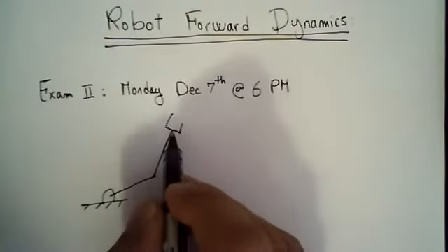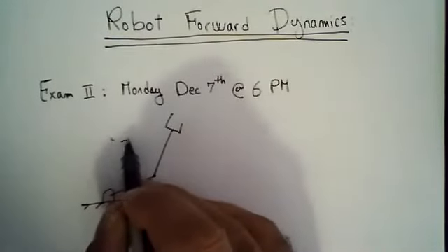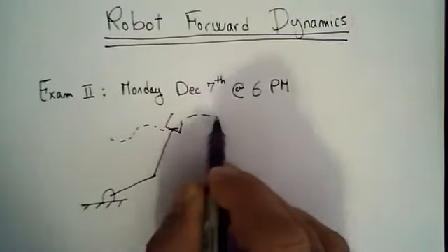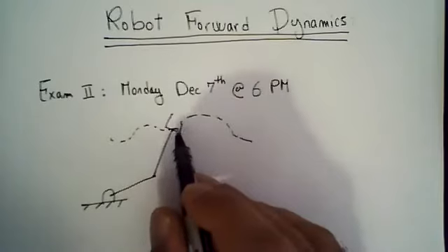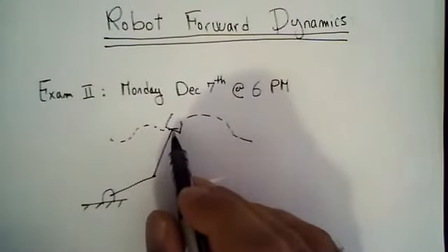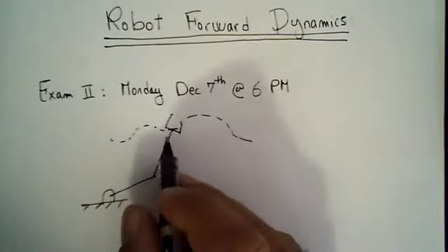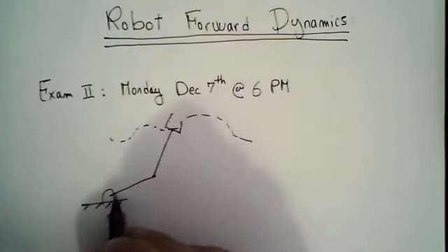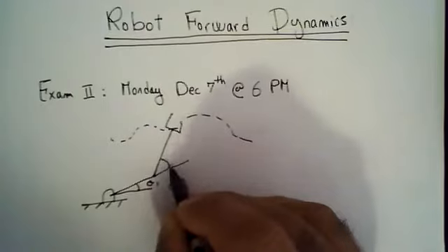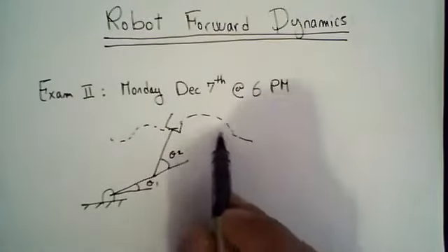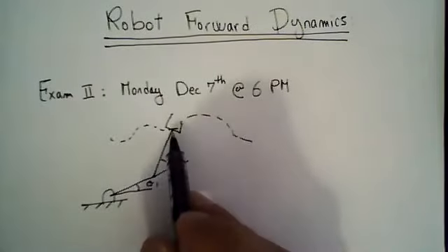And if I would like to move this robot, or the end effector of this robot, along some trajectory, and I know this trajectory as a function of time, basically, I know the x of it and then the y of it. So far, what we have been doing is we have been able to solve the inverse kinematics, right? And if I have this theta 1 here, and this guy is theta 2 there, I'm actually able to solve theta 1 and theta 2 for any pose.